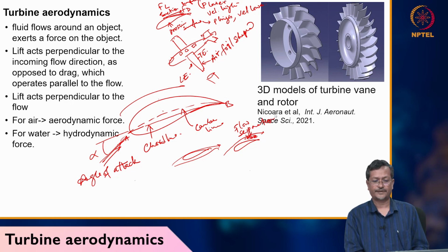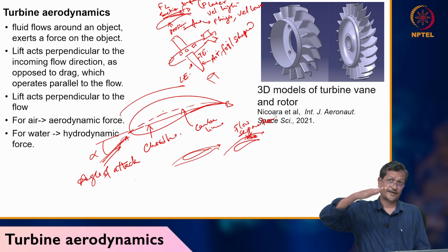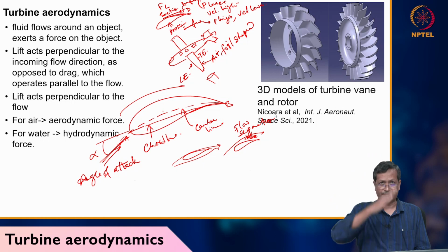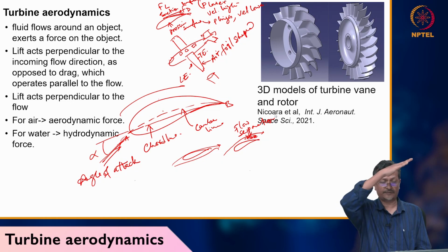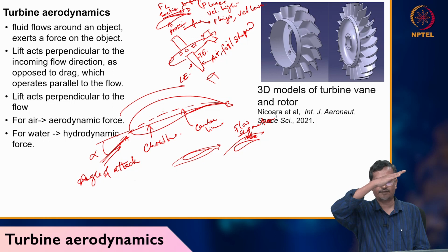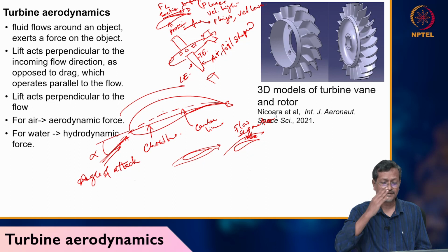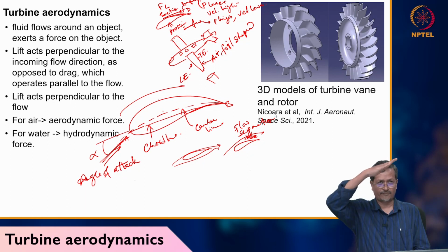Whenever any airfoil is designed, scientists will consider this flow separation point. If flow is getting separated quickly, then it will not get lift. Rather, let's say an airplane is moving up and you make a very large nose angle. In that case, flow will be separated and the flight will fall down quickly. That's why, whenever a flight is going through the runway to lift off, it will have a proper angle. If it is not getting the proper angle of attack, then this flight can fall down quickly.